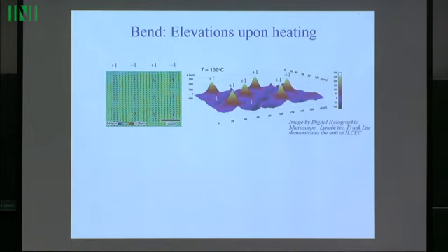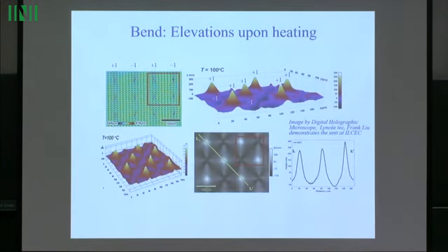Each center at which we had +1 circular defect suddenly transforms into a nice hill that protrudes up away from the substrate. The profile is rather well developed for a film that is, in this case, about 5 micrometers thick. You have the amplitude of these protrusions at the level of about 250, slightly more, nanometers.